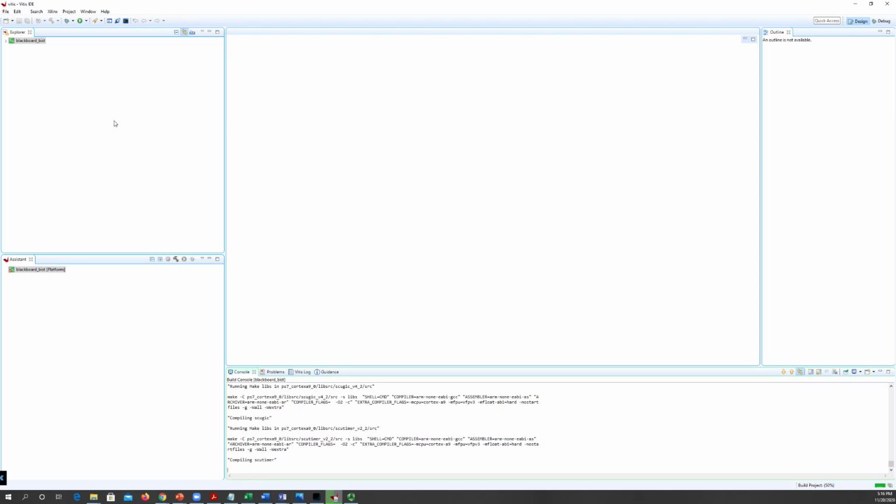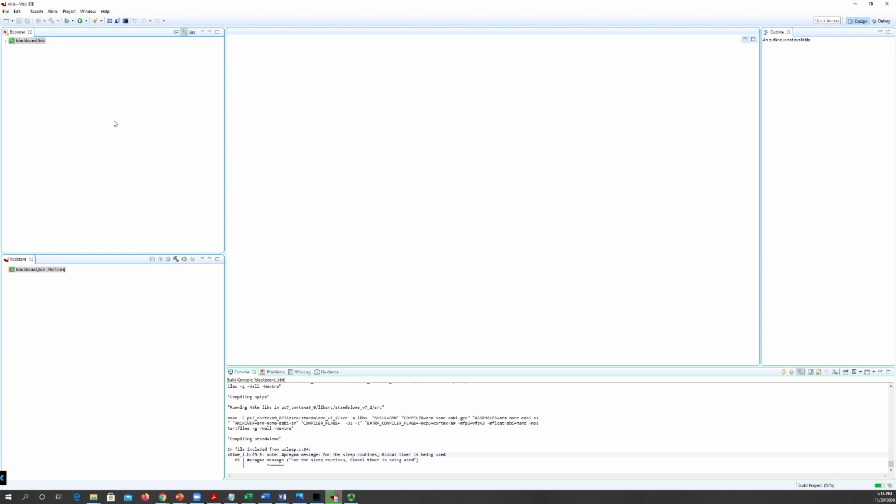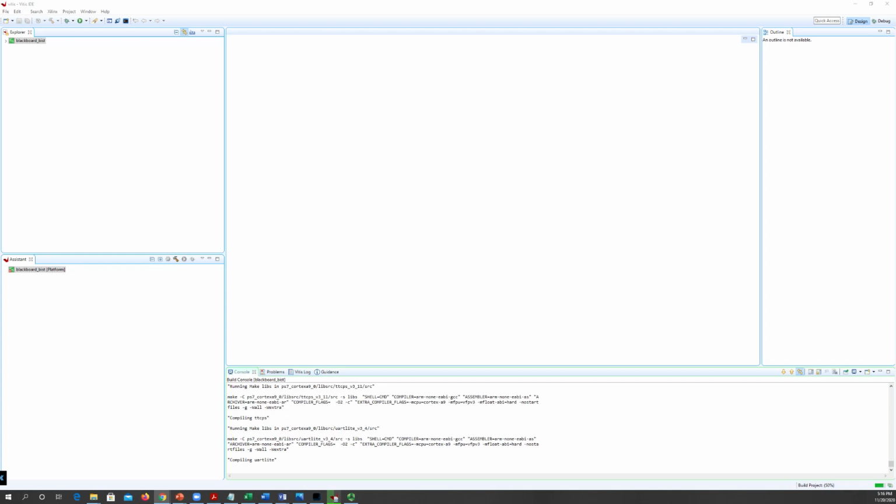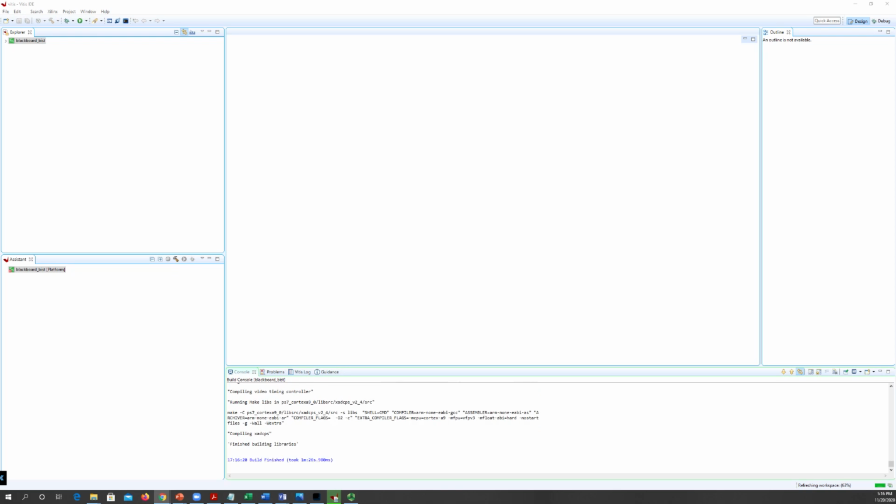So now once this process finishes, we're going to have to go ahead and apply these settings to a new application project. So the steps are: configure the board with the information in the blackboard.xsa project, and then set up a new project that is going to draw from that stuff when we write software.